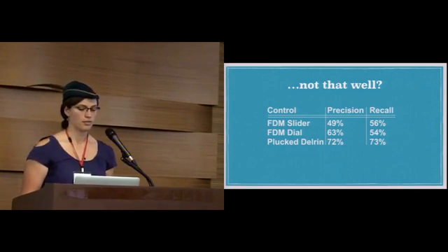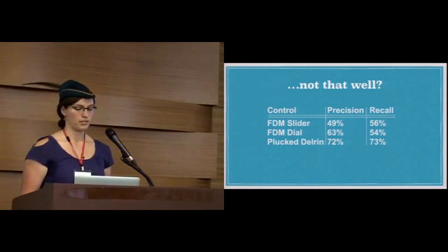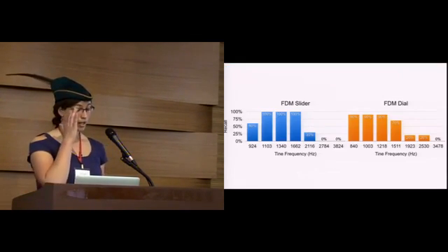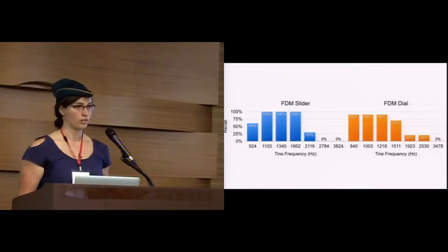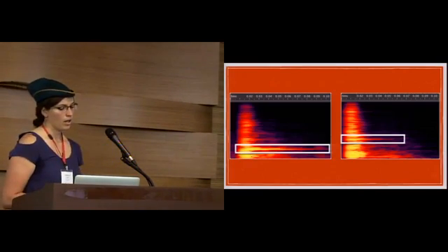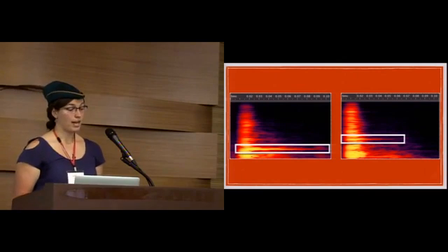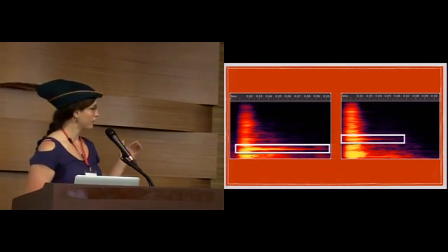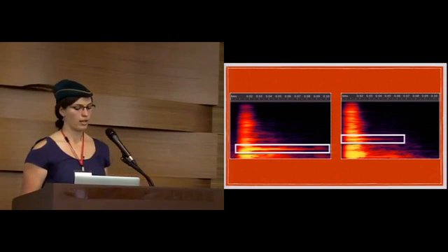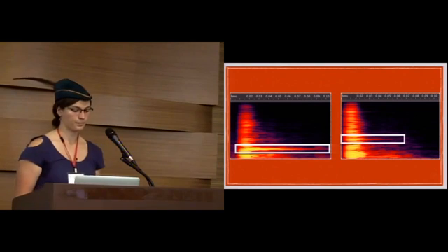In the first set of experiments we did, on a set of 7 distinct frequencies, we got precision and recall hanging around 60%, and it wasn't very encouraging, so we dug a little deeper. It turns out we have a very hard time distinguishing frequencies in the range around 2000 Hz and above. Higher frequencies decay faster and have lower energy, while you see that the lower frequencies have more energy for a longer period. Our current algorithm just doesn't have enough time to make a choice on these higher frequencies.